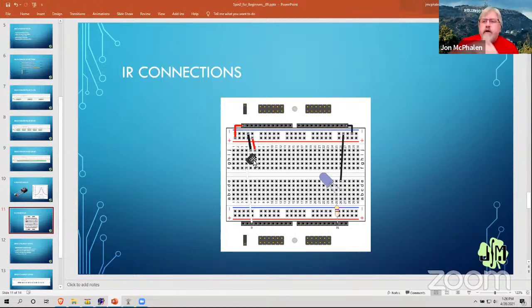And once I've put the sensor into the board, I just twisted it a little bit so that it can kind of see this IR LED. Here, this resistor, I'm using 470 ohms, but anything will work, I'm sure. Anything between 100 and 1K, and you could probably go higher than that because there's only an inch and a half between here and there.